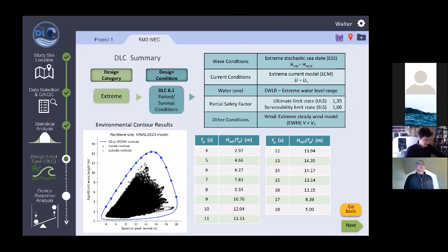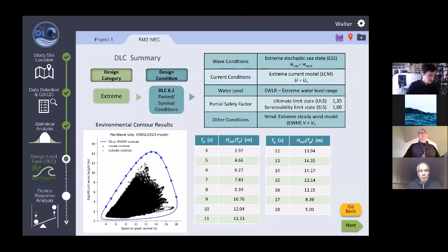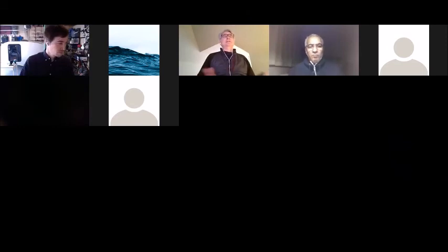One thing that is a little more challenging with the current side is we model the environmental wave load condition, the input that goes into, say, WEC-Sim or a dynamic simulator, just using a simple modeled spectra and then an inverse Fourier transform. In the case of currents, we would ideally use a good tool like TurbSim, which was initially developed for wind turbine design. But you can think of TurbSim as almost like an environmental load conditions simulator, right? That provides the inflow inputs for designing a wind turbine, or in this case, a hydrokinetic turbine, right?